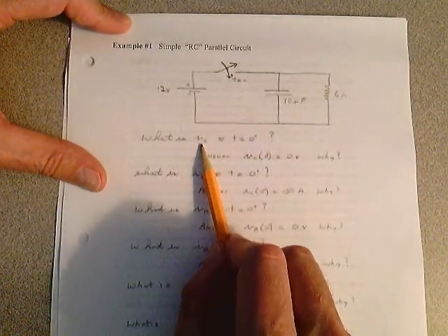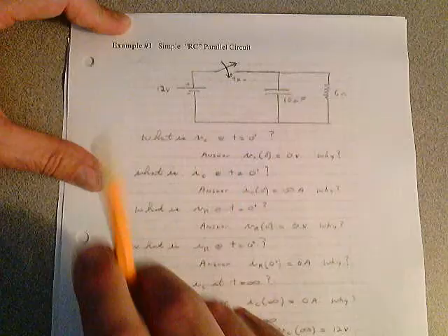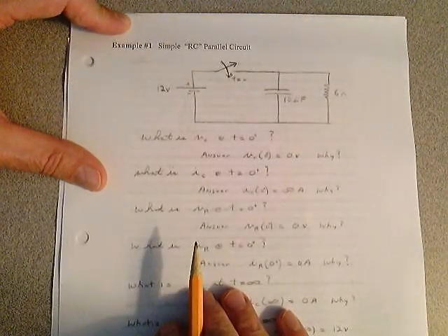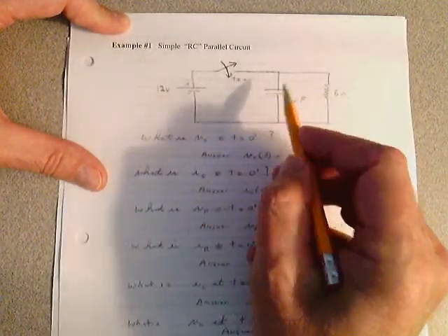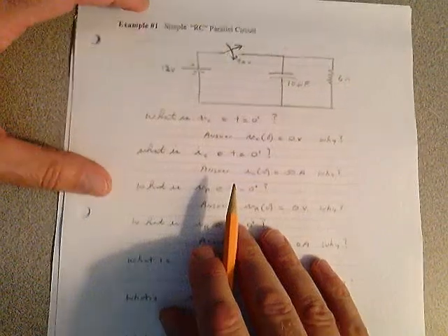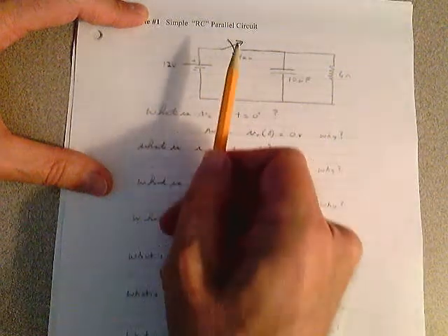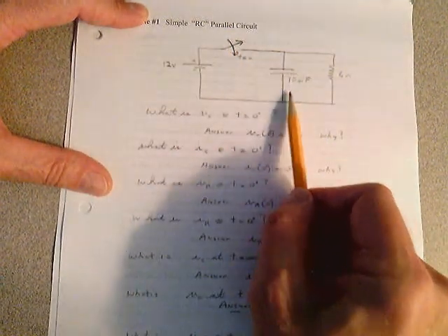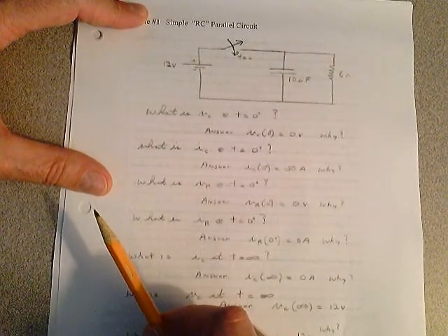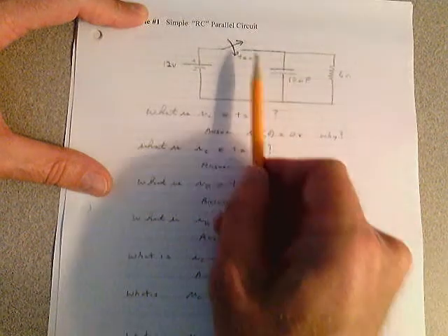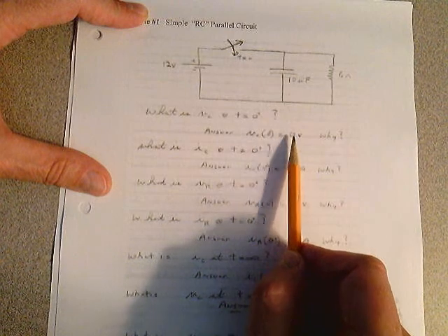And I want to know what is the voltage with respect to time across the capacitor at t equals 0 plus. In other words, you throw this switch, and at the instant above 0, t equals 0 plus, what is the voltage across that capacitor and why? Well, you know that at time t equals 0 minus, that's an open switch, so the voltage there is 0 with respect to ground here. The voltage is 0. And you know voltage can't change instantaneously across the capacitor. So when you throw that switch, the voltage here at t equals 0 plus has to equal 0 volts.